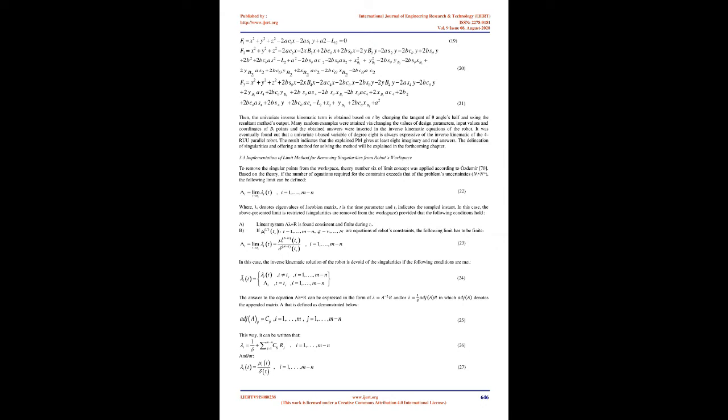3.2 Solving the inverse kinematic problem and obtaining the determinant. According to the transformation matrix and the eightfold constraint explained in the first part of the present study, the matrix's determinant and singularities can be specified. The resultant method was used to solve the inverse kinematics problem of the robots. The resultant method serves the elimination of one or several variables from an equation system in such a way that the finally attained equation encompasses the effects of all the equations.